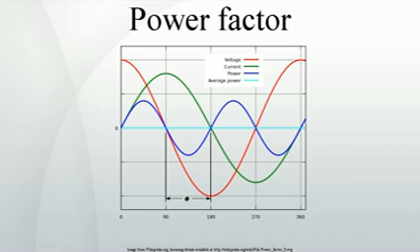Importance of power factor in distribution systems. Power factors below 1.0 require a utility to generate more than the minimum volt-amperes necessary to supply the real power, watts. This increases generation and transmission costs. For example, if the load power factor were as low as 0.7, the apparent power would be 1.4 times the real power used by the load.